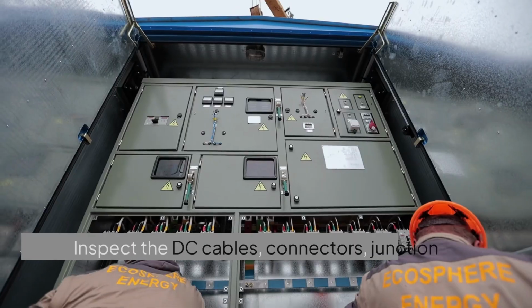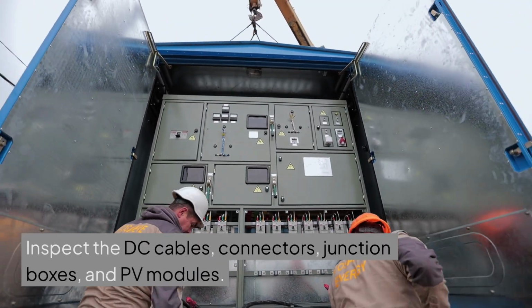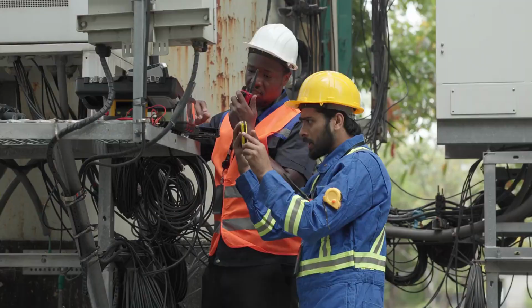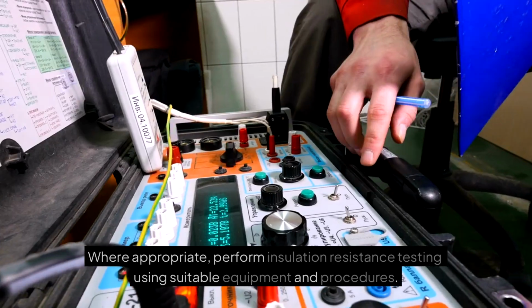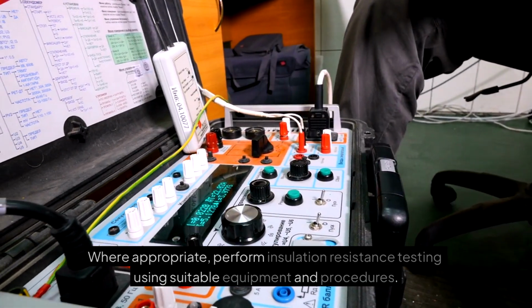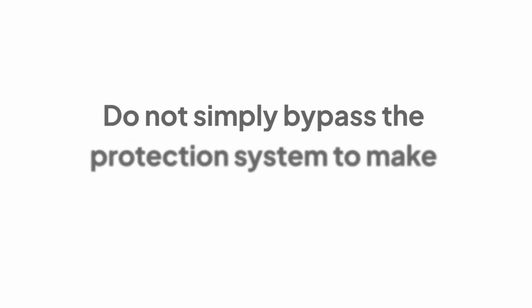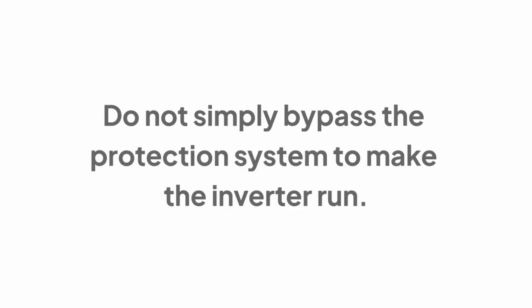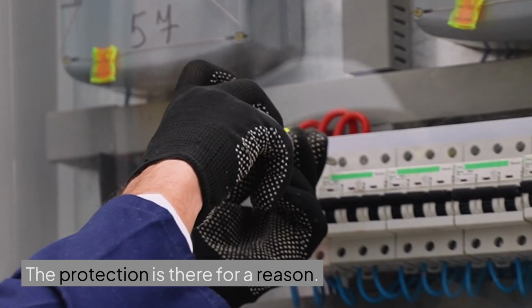Troubleshooting. Inspect the DC cables, connectors, junction boxes, and PV modules. Check for physical damage and moisture. Where appropriate, perform insulation resistance testing using suitable equipment and procedures. Do not simply bypass the protection system to make the inverter run. The protection is there for a reason.